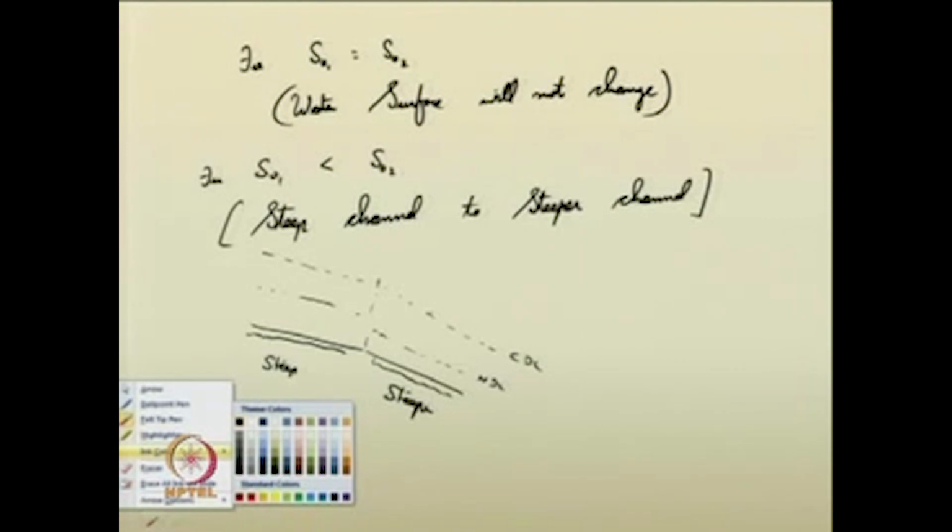Which is the theoretically possible one? Here this is zone 1, zone 2 and zone 3. If the water surface goes below into zone 3, the water surface slope has to be always positive in zone 3.